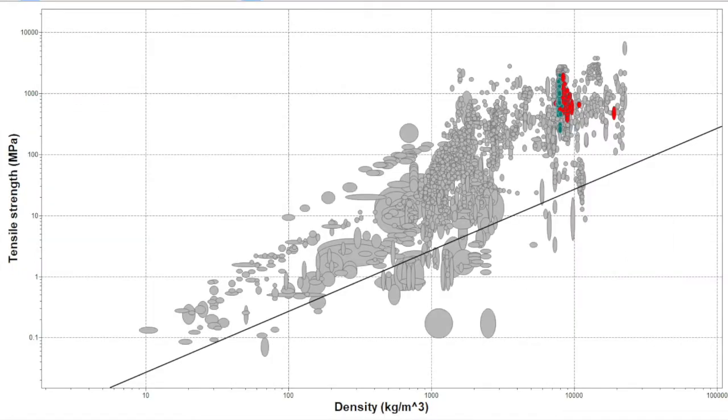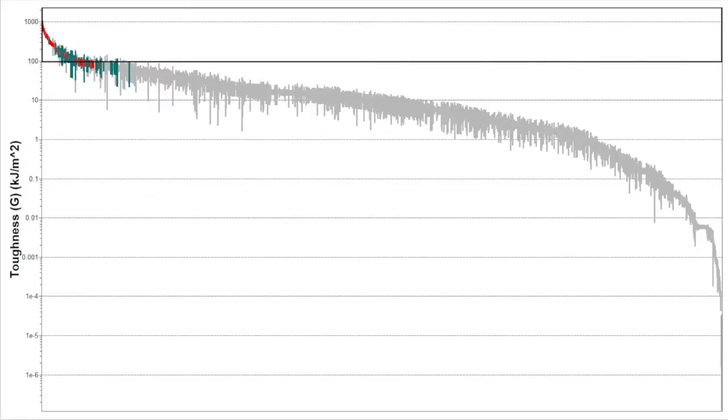It was also important that the material could have a high tensile strength relative to its density, such that the lock is not too heavy and cumbersome, although this is not as important as the shear characteristics. Finally, as mentioned before, the toughness of the material, and thus, passing all other requirements, the toughness must be maximized so that it will not shatter if it is hammered or impacted by a sudden force.